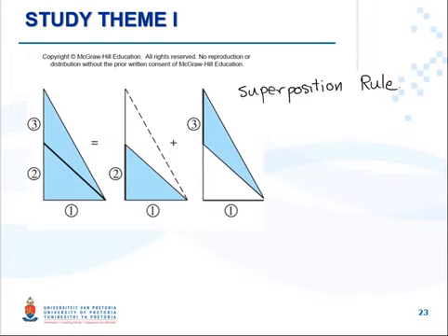The best approach is to find the view factor through geometries whose view factors we know. We need to see how we can incorporate standard geometries, whose view factors are easy to find from the table, in order to find the view factors of non-standard geometry.